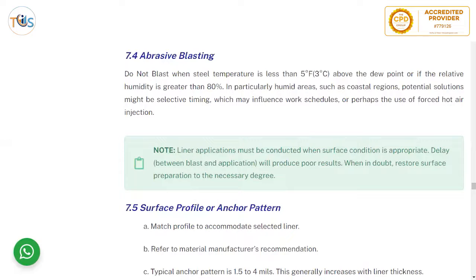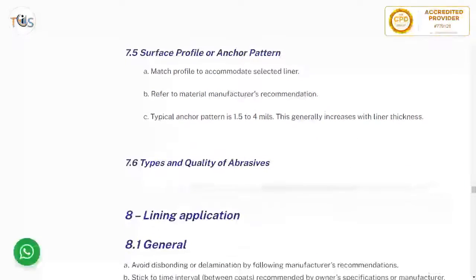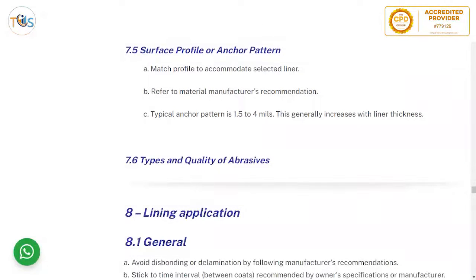Liner application must be conducted when surface condition is appropriate. Delay between blast and application will produce poor results. When in doubt, restore surface preparation to the necessary degree. Surface profile or anchor pattern: match profile to accommodate the selected liner.